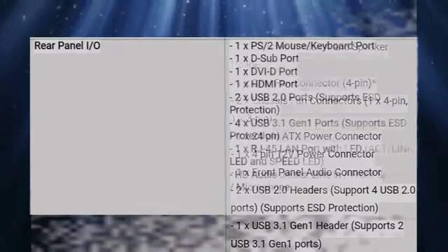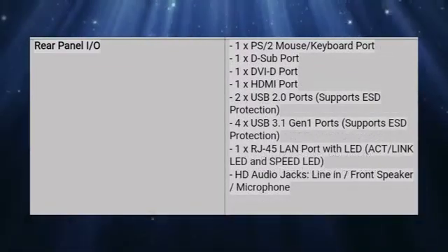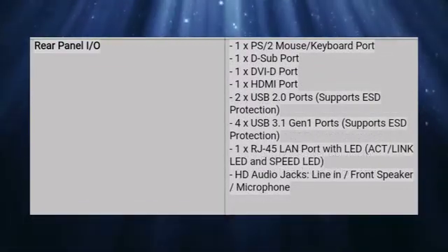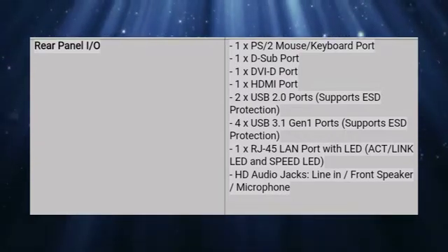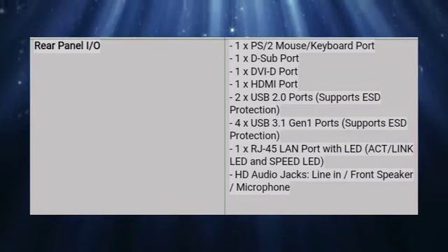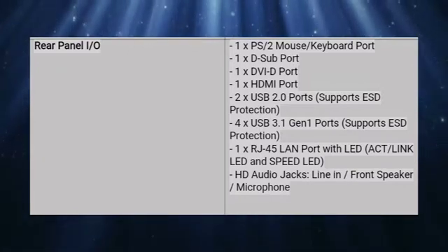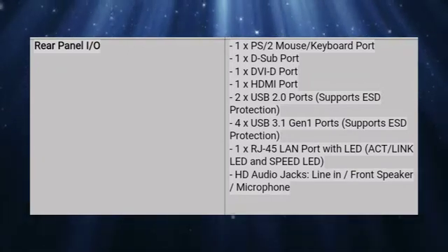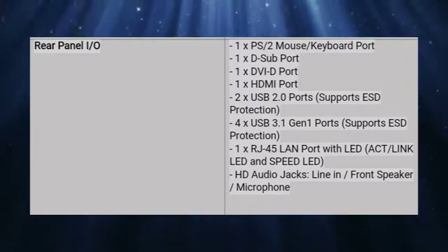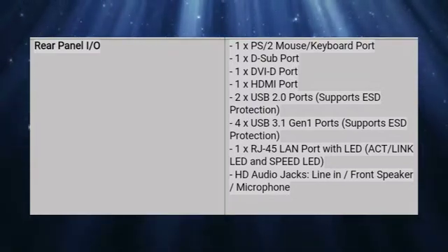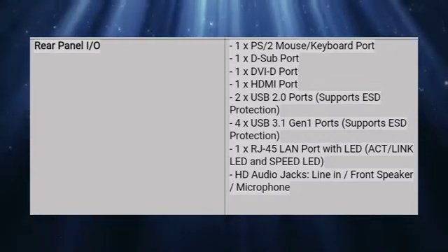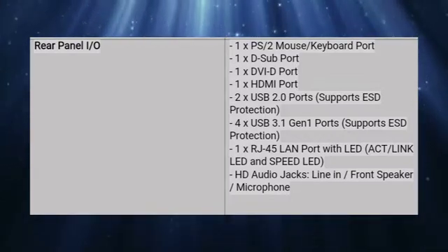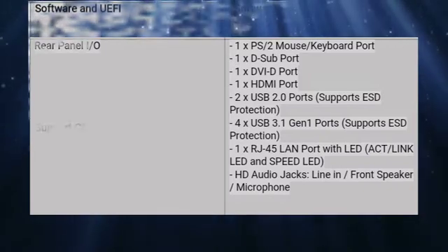For the rear panel, it has one PS/2 mouse/keyboard port, one D-Sub port, one DVI-D port, one HDMI port, two USB 2.0 ports supporting ESD protection, four USB 3.1 Gen1 ports supporting ESD protection, one RJ-45 LAN port with LED, ACT/LINK LED and SPEED LED, HD audio jacks: line in, front speaker, microphone.